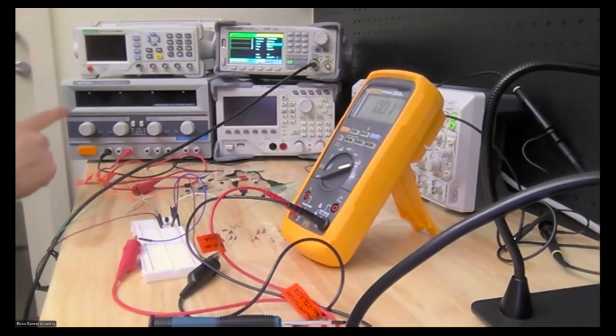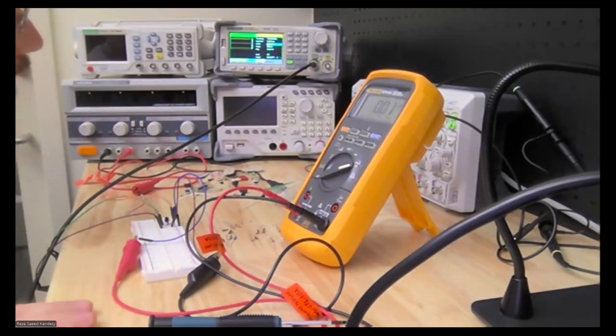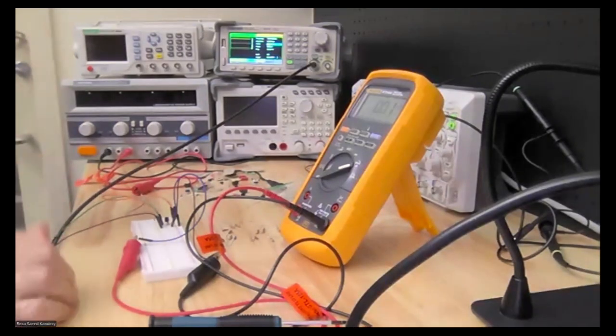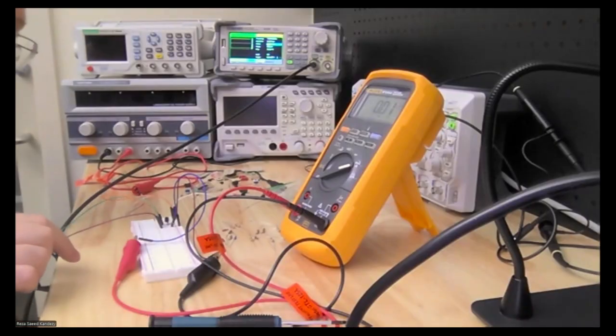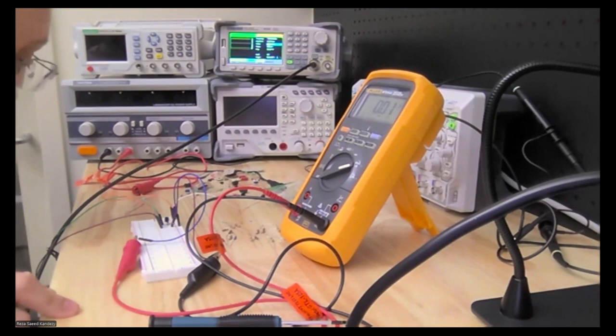Okay, so you can set the drain and source at a constant voltage and switch the voltage between gate and source. By that you have a series of data points, and we know the threshold is 2 volts.